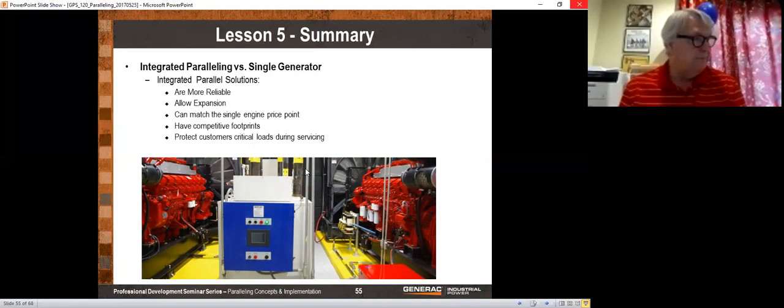All right. Is it possible to perform peak shaving with generators set up for paralleling? Is it possible? Yes. Is it practical? Typically not. Now let me give you an example that we have. We test motors. We have a motor rewind shop, and when we test a big motor, it takes a lot of power, and therefore it's going to set a peak for the month that would cost us a lot of money. So what we actually do is fire up our standby generator, and then we use that standby generator in order to test that motor, and that way the motor is being tested on standby generator power rather than